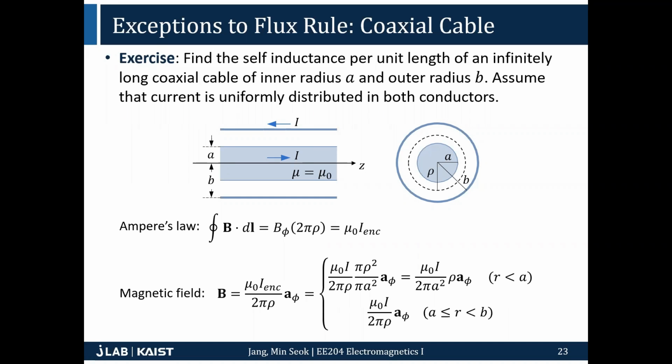Then what? Is there any good way to evaluate your self-inductance? Because it's difficult to obtain magnetic flux in this case. So even though you know B, psi is difficult to evaluate. But how would you evaluate L in that case? Here again, one circumventing, alternative way of obtaining L is beginning from magnetic energy.